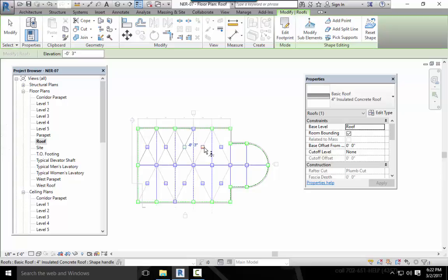But that's okay. I prefer that you do it this way so that you understand when you're laying your roof out what all those elevations really are. Now with this roof design, what the designer is saying is at this low point that we're adding, each one of these there would be a roof drain. And if I was designing the roof as the architect, I'd want to push this water to the outside walls and have scuppers and drains at my outside walls. But since this isn't a roof design class, it's Revit, we won't critique the author's design of the building.